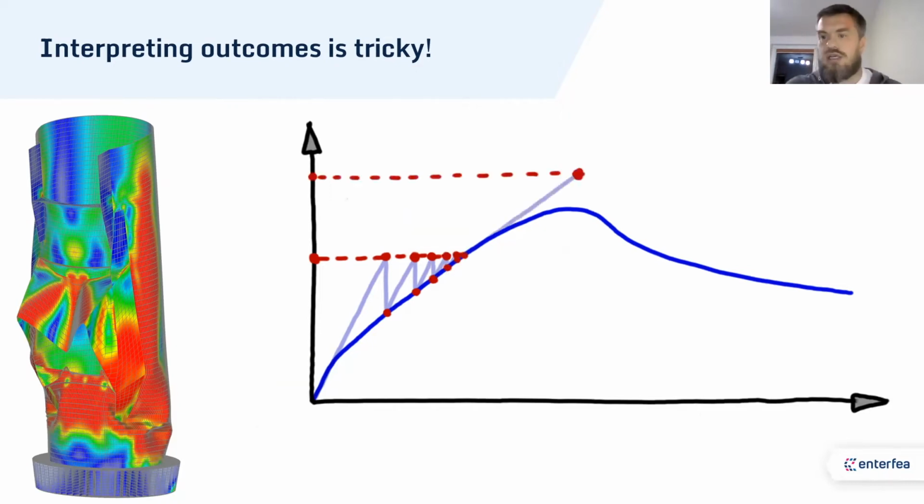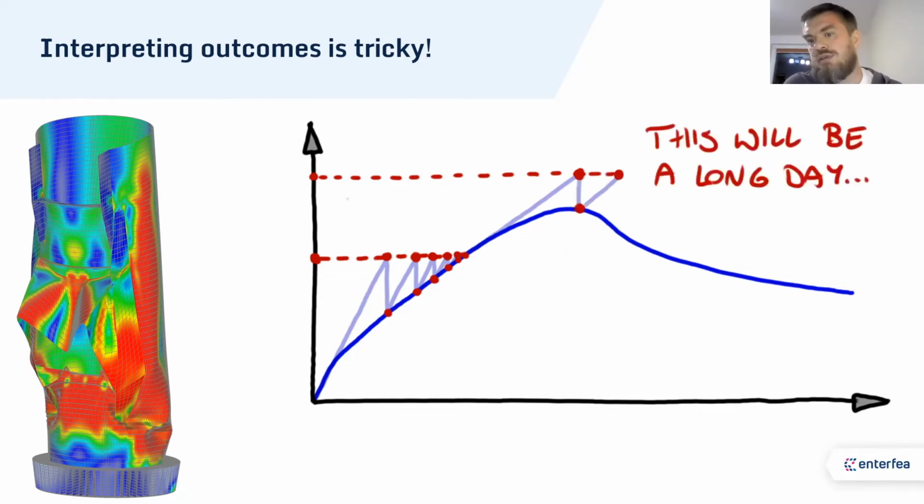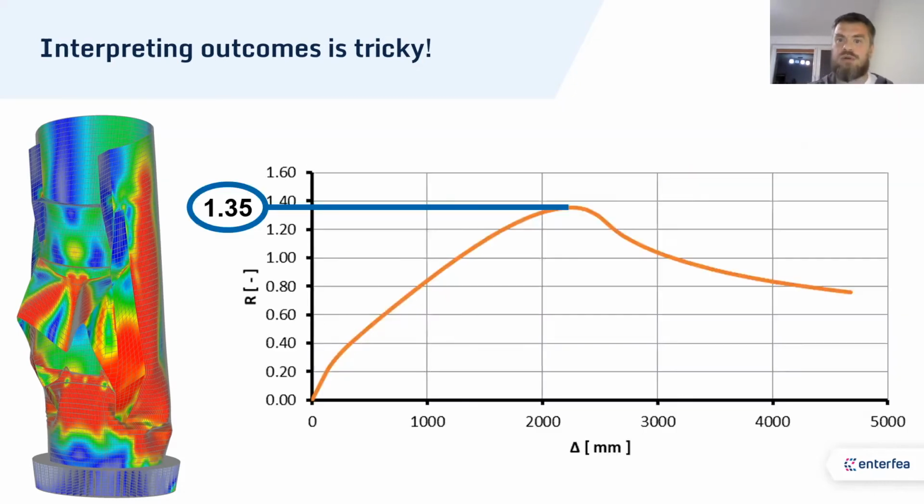Of course, this is not the only problem with convergence. You can also try to load your model with loads that are way higher than the capacity of the model. And then you can clearly see that it will never converge. So non-convergence must be the most hated error message of FEA. And to solve this, you would actually need an arc length method to solve this problem. And if you would use arc length method that iterates the load a bit differently, you will notice that this curve, the equilibrium path, has a clear tip. The capacity increased and then it decreased, so the model failed.